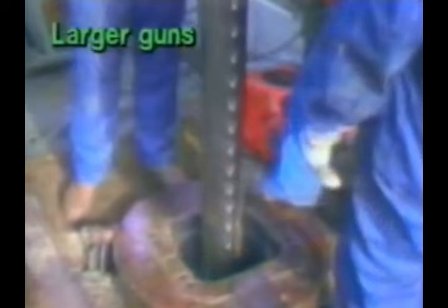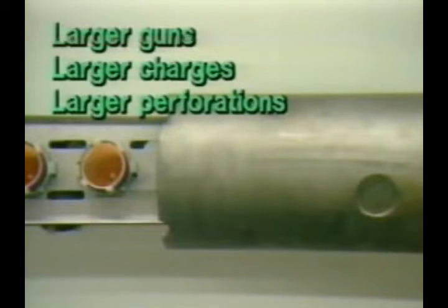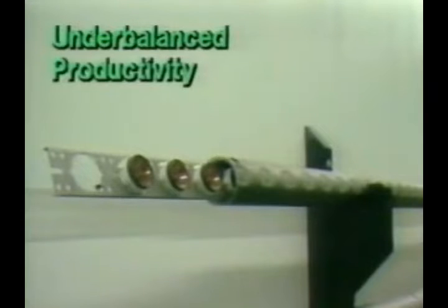Generally speaking, the larger diameter casing guns run via wireline will carry larger charges, and thus give larger perforation diameters and greater penetration depths than the smaller through tubing guns. Through tubing perforating, however, is a more practical method for underbalanced perforating than using conventional casing guns, and underbalanced perforating can help maximize productivity.